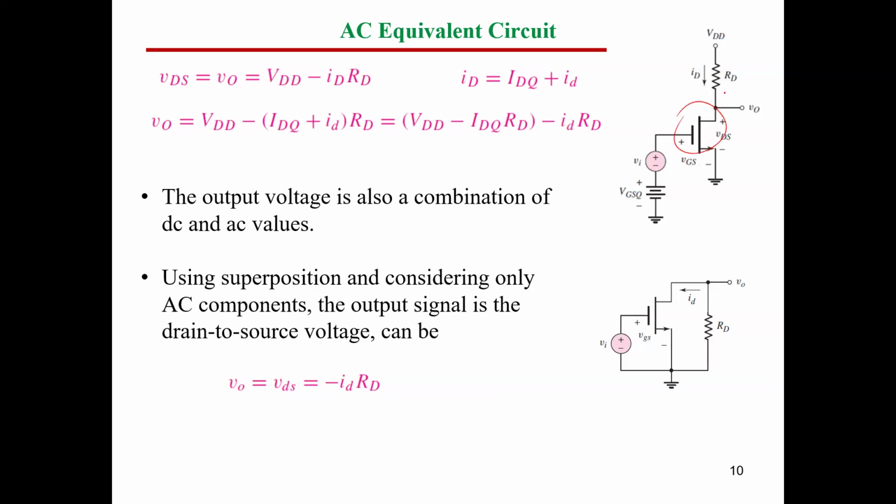We need to convert this to what's called the small signal model. Small signal model, guys, means convert this to an equivalent circuit. Equivalent circuit means passive parameters like RLC, and it means current sources, voltage sources. So we need to have an AC equivalent circuit. AC, why? Because we are going to represent this for the amplifier. So we need to make the AC analysis.